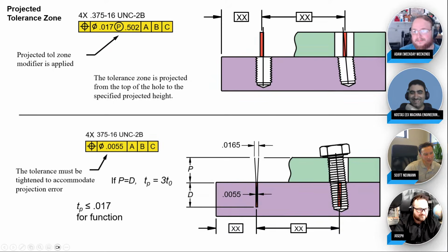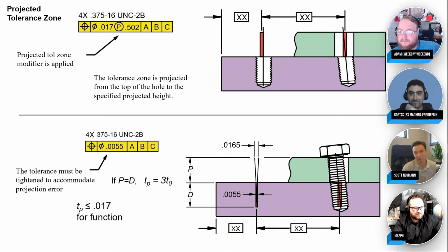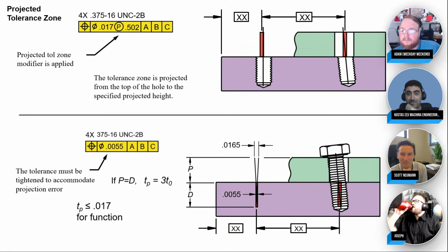The thing is too, I say that, it's just going to cause interference, and really what happens, you put the torque wrench to that thing, it's going in, right? So you're going to end up cross-threading stuff is what really happens. Cross-threading is shifting the top plate, and then another part doesn't fit, and then another part doesn't fit, and then you're chasing. You think that the problem is with the other part that doesn't fit, where this is where you made the error. It's so much simpler to just think of it and specify it properly.